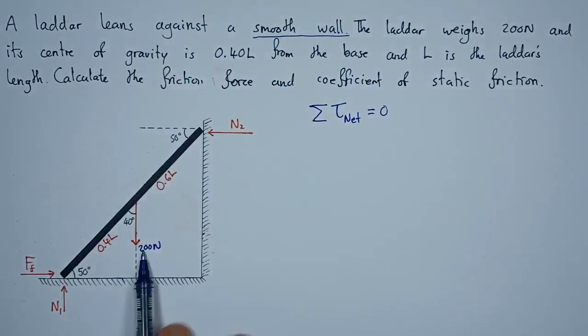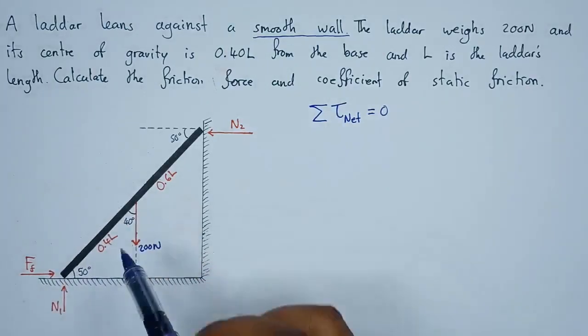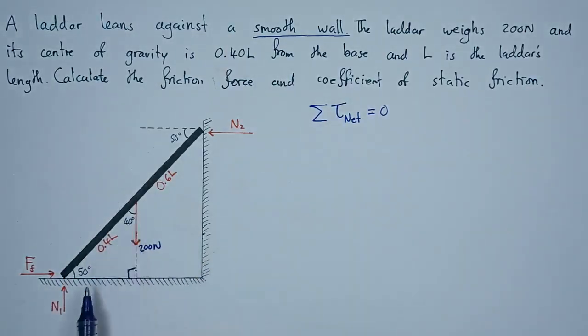Starting with this force that we have here, we're going to say we need to find the force times this distance that we have here. So what is this distance here? Well, depending on which angle of interest you take, in this case, I'll just use this 40. If this is my triangle, my right angled triangle, and my angle of interest is 40, it means that this side is the opposite.